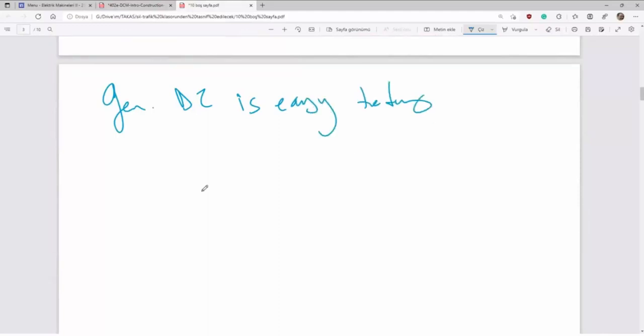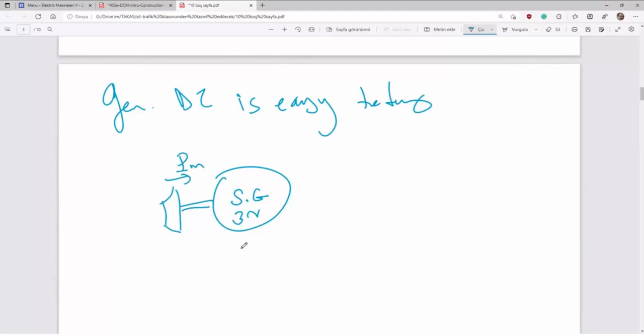For example, you can generate AC by using synchronous generators, let's say 3-phase. You apply some mechanical input power to the synchronous machine. Let's say here's the excitation circuit, apply some field current. And then you will induce or generate some AC here on the armature terminals.